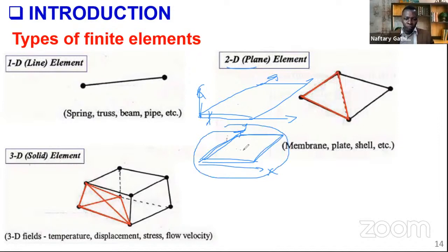Because there is a material, there is not a void inside here. When we are talking of a single line, it's like this place was a void, like when we have a truss, right? So we're just taking the members and then the middle part is a void. But now this is a plate, so this part is not a void. So in finite element analysis, we want to interpolate. Let's say it's a plate being heated here, you're applying heat. We want to get the temperature at the midpoint, because there is a material there. So that's why the 1D line element cannot be applicable here.